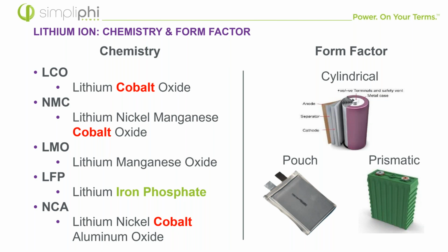So pouch cell, oftentimes I think about a laptop or a cell phone. This is commonly a pouch cell. These are a bit tricky to use when it comes to large-scale batteries or building out a battery big enough to cover house demands and things like that. They have these small tabs, if you can follow my mouse here. Those are actually the positive and negative. So when you have a battery using these pouch cells, you might see some shorting oftentimes, or some swelling and cracking.